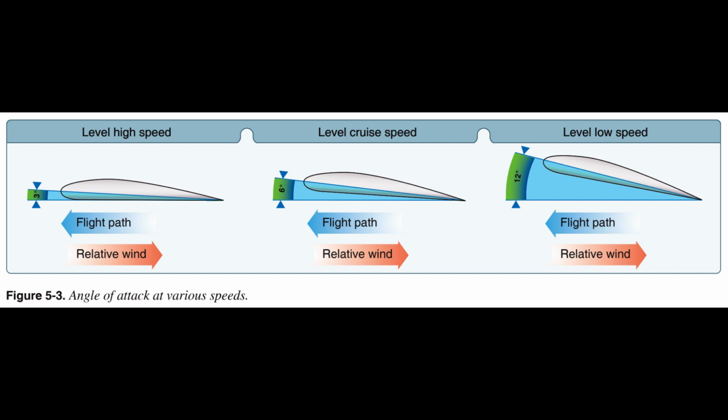If thrust decreases and airspeed decreases, lift will become less than weight and the aircraft will start to descend. To maintain level flight, the pilot can increase the AOA an amount that generates a lift force again equal to the weight of the aircraft. While the aircraft will be flying more slowly, it will still maintain level flight. The AOA is adjusted to maintain lift equal to weight. The airspeed will naturally adjust until drag equals thrust and then maintain that airspeed, assuming the pilot is not trying to hold an exact speed.